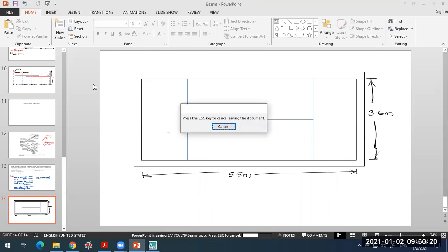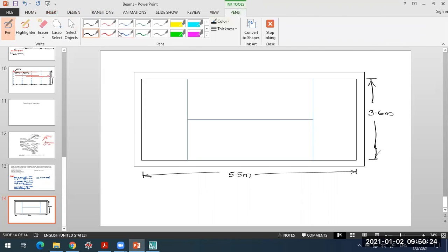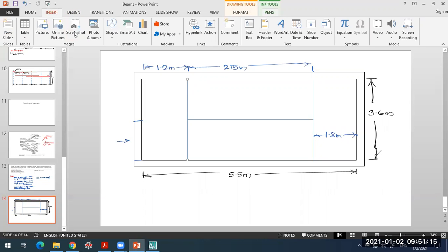So as per our calculation, out of 5.5, what I have here is 1.8 meter, and this is 2.5 meters. And this will be how much? 5.5 is the total size. 5.5 minus 2.5 minus 1.8 is 1.2 meter. What is left over here is the space which is available at the entrance. Somewhere here the door will be there, or the opening entrance for the staircase hall, and these will be the steps. So this is our plan of the staircase hall.